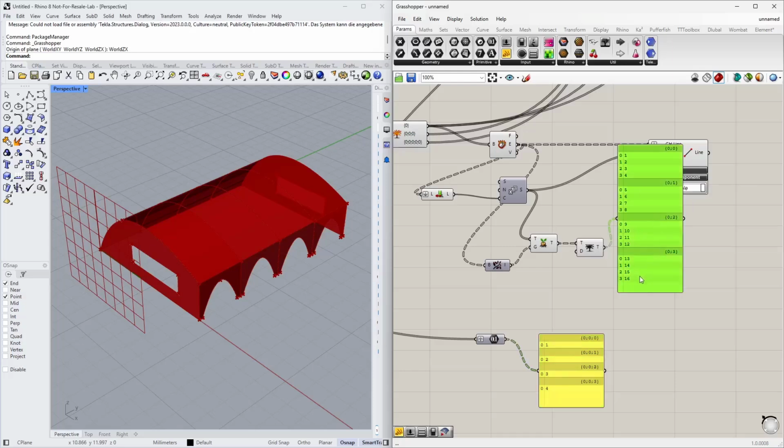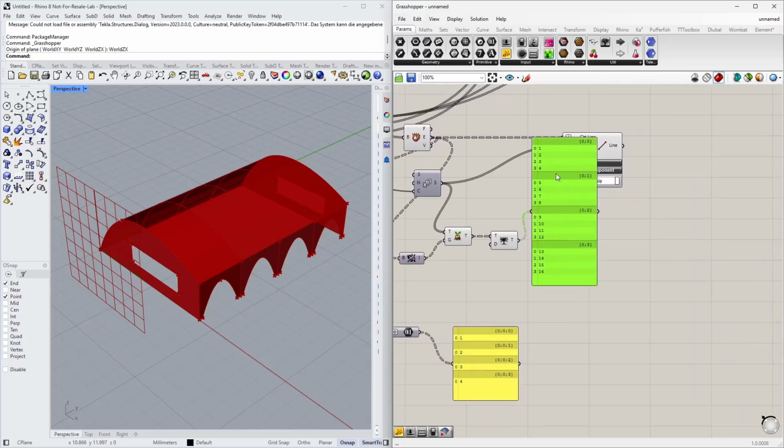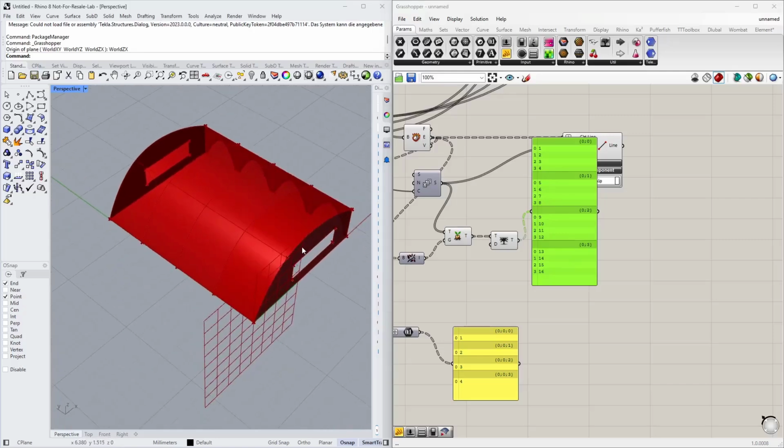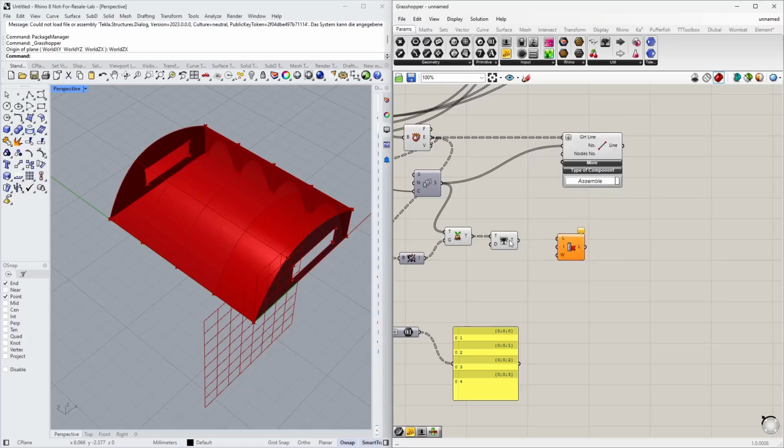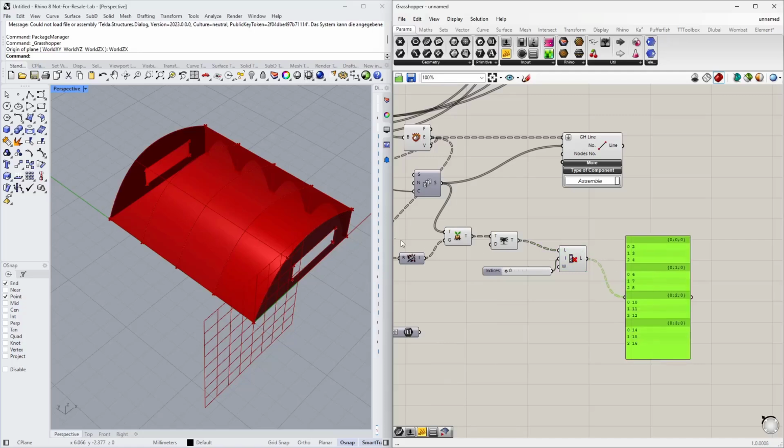Before I do that, I have to get rid of one of those index numbers, because I want to define a line hinge, or let's say differently, I do not need a line hinge on the bottom lines. I have a line support down here. There's no reason for a line hinge. So I get rid of the index number 0, which is always the bottom line for each group. Easy task, cull index. So we remove one index from the list, the index with the number 0. So now only 3 lines will remain here.